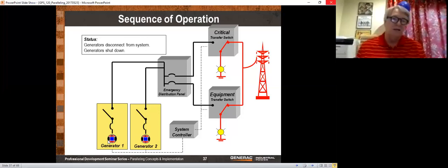There is also a second level of redundancy. If you want to, you can go out there and just start generator 1. You do that by turning the switch to manual. So there's auto, off, manual. You turn it to manual, boom, the generator starts. And then there's a little button on the screen that says manual mode parallel. You push that button. That's all that's necessary in order to parallel that generator to the system. And that's all that you can do. We don't let you go in and fix this thing.